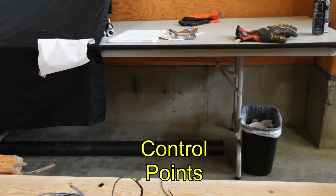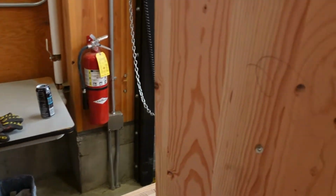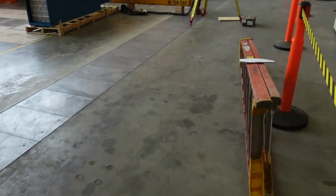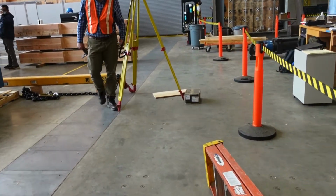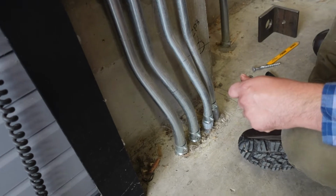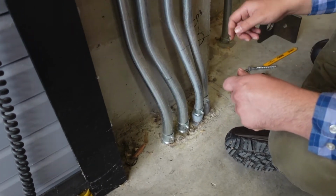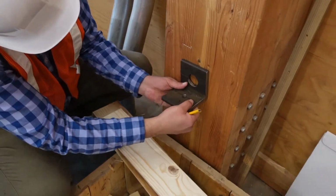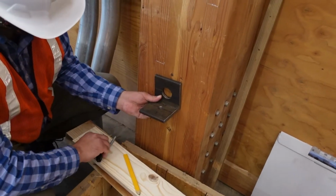Before scanning the building using the LIDAR devices, it was necessary to perform a survey of the laboratory and the building specimen using a total station. This is important because we will need to locate the cloud points resulting from the LIDAR scanning in a reference 3D space, being able to detect differences in the lateral deformations for future scans once the lateral test is performed.